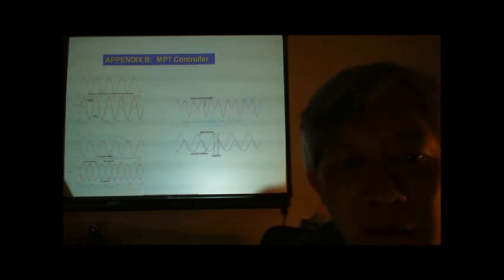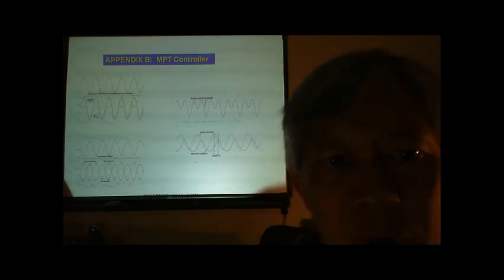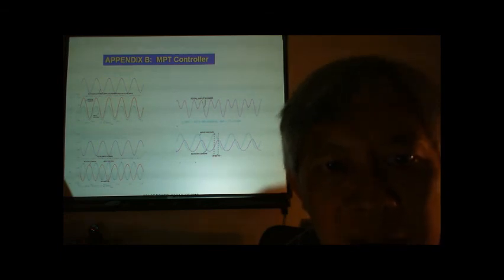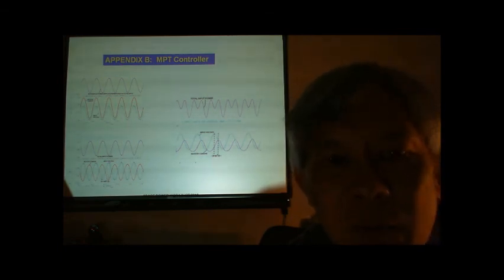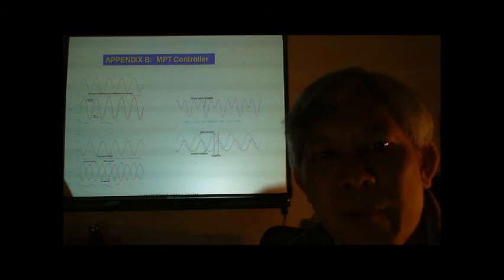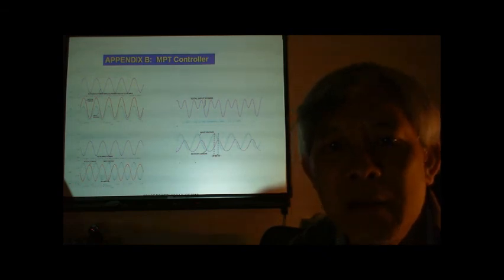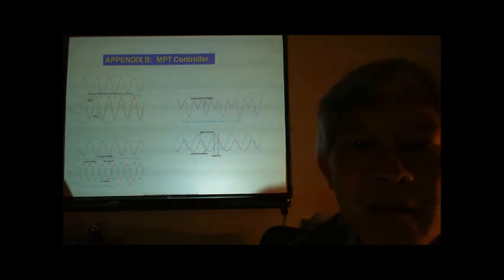When the system delivers the output current ripple shown in the purple or red color, it shows about a 90-degree phase shift with respect to the sourcing voltage in blue, signifying that the system is already around the peak power point or at the peak point of the PV DC characteristic.